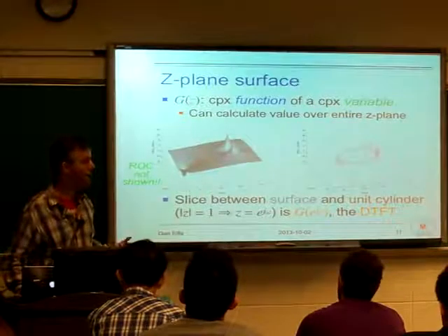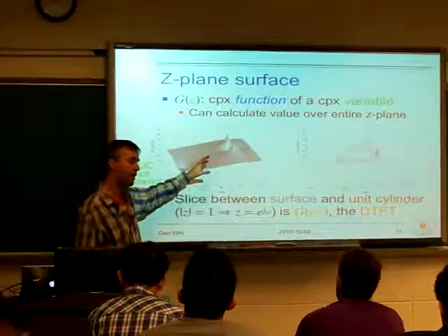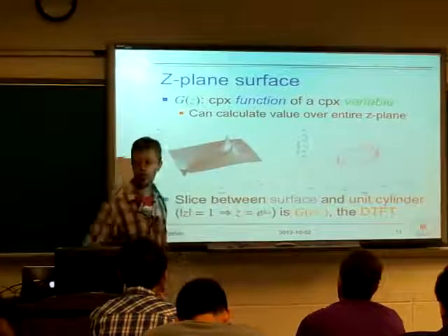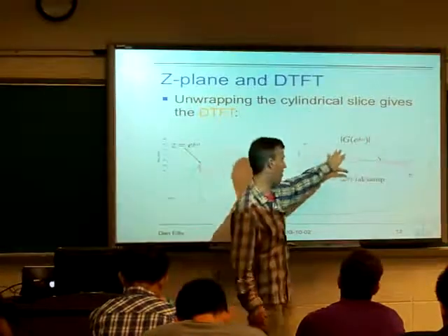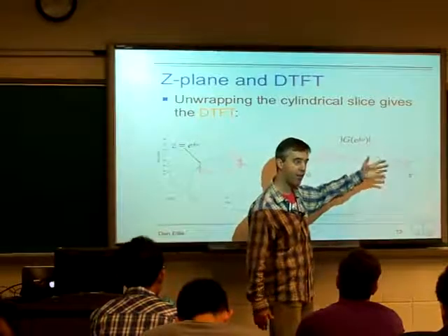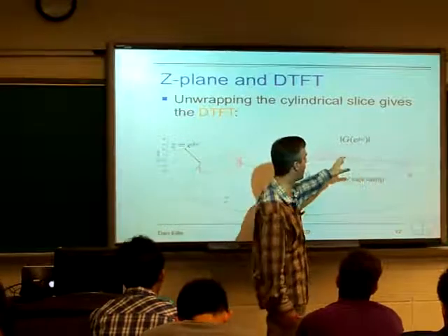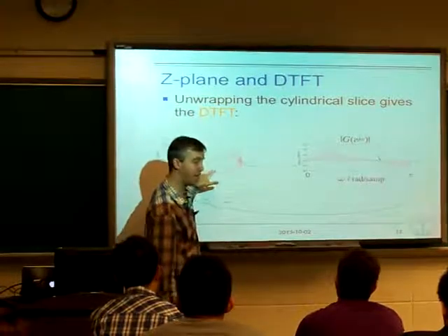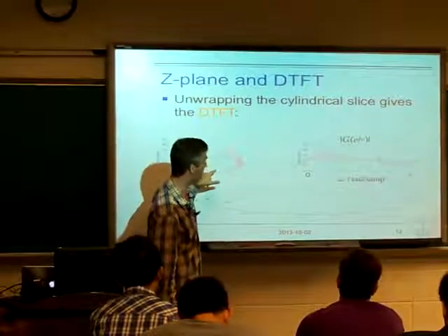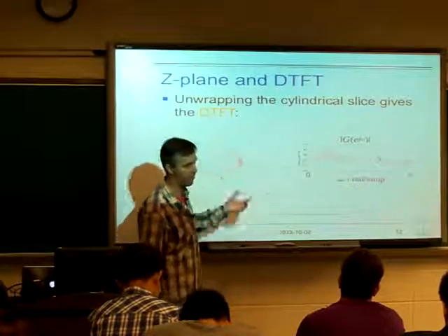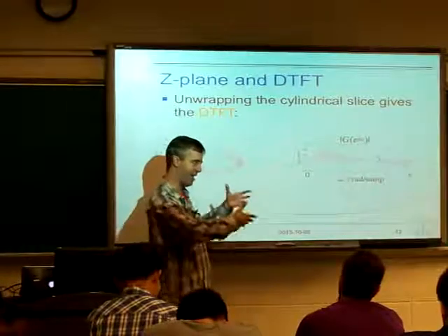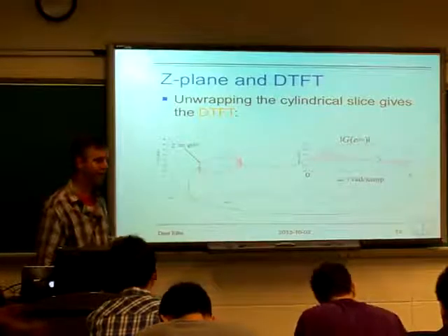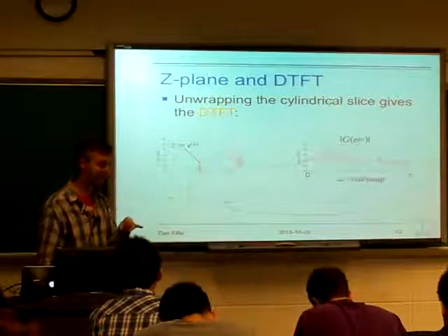And that's the real power of thinking about discrete time systems and signals in this Z-transform domain. Suddenly the features of the Fourier transform, which is very, very concrete, right? It's how much certain frequency components are present, or how they're going to be treated. These features then relate to these fundamental properties, the roots of the Z-transform closed form expression, and they relate in a very simple and intuitive way: poles tend to lift it up and zeros tend to push it down. So that's the point, and we're going to continue to pursue that for a bit.